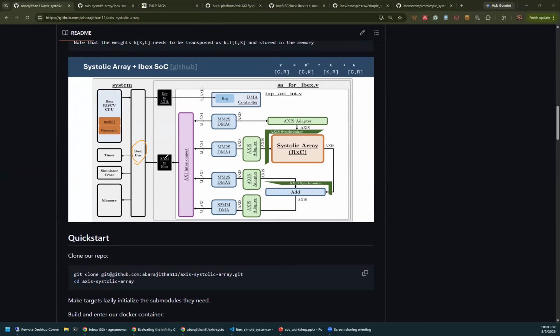So what I did was basically I used this AXI interconnect. Another thing is I wanted to play with the interconnect as well. So I use this, and this interconnect has 4 slave ports, and I connect these master ports to them. On the other side, it exposes 1 master port. So you can combine all 4 master ports into 1 master port through this interconnect, right? So that's what I did, and that way you're only giving 1 port to this.